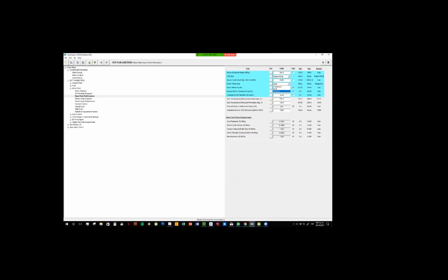And in cyclone, it mixes with air, swirling the air and the pulverized coal in this case, right? The boiler efficiency, you have a column that says calc, that means the model is going to calculate it, right? So that's the efficiency that the boiler should have. If you know the efficiency of your particular boiler, you can unmark this column and change it.